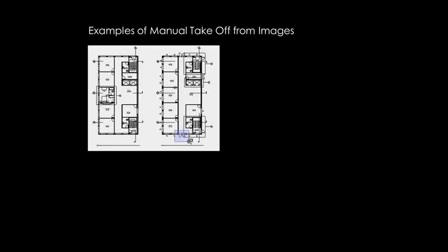There's a very easy integration between the model. But let's say you don't have BIM. Or even better, I know firms that have used QTO but they don't have BIM models as early as they would like to, and they just start with some basic conceptual schematic plan that they may receive. So once they have some kind of conceptual schematic plans, you don't have to wait for the model to be built. You can start using images, scan drawings, PDFs as they are, or DWGs if you have them. So these are a couple of examples of plans.